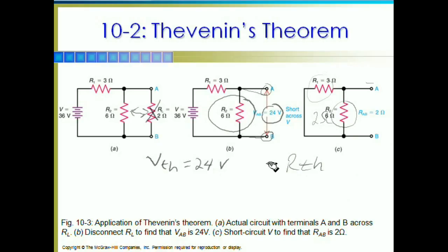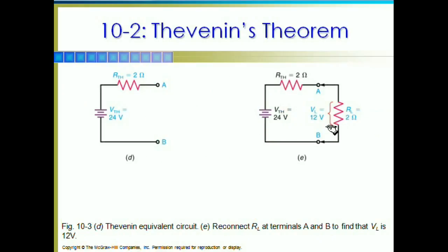Now I'm ready to set up the circuit, and at no time do I have to go back and repeat over and over and over again the calculations of the equivalent resistance, current, voltage. Now that I've got this circuit set up, I can just stuff my load resistor in and treat it like a 2 resistor series circuit. And it doesn't matter what value of load I put in, I can easily calculate my load voltage and my load current.